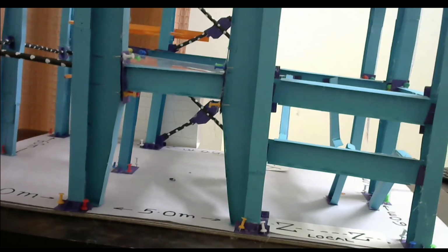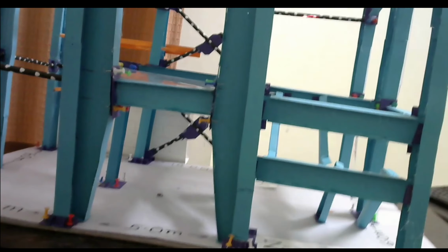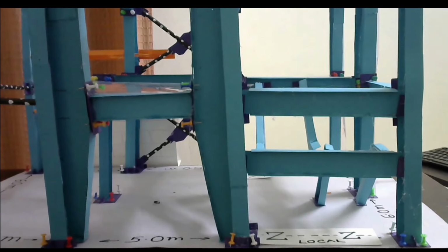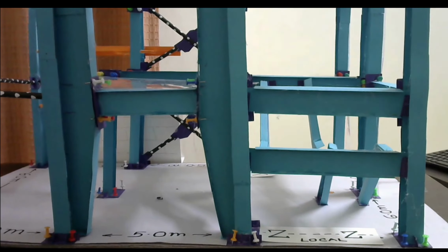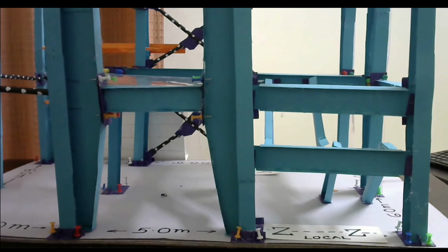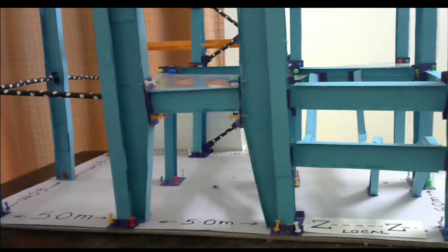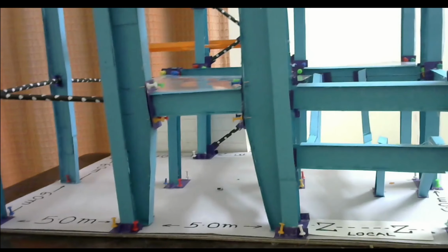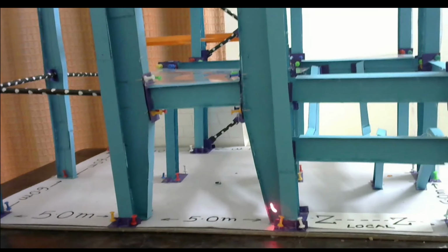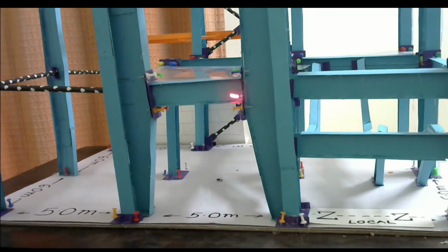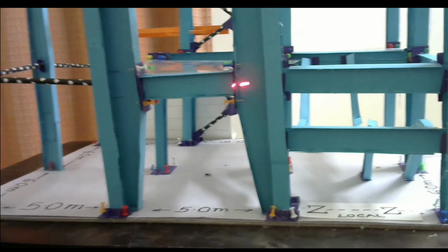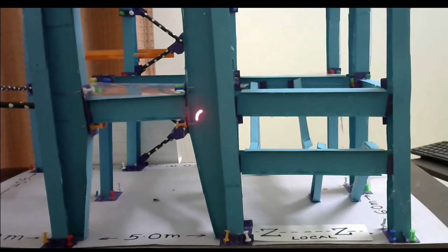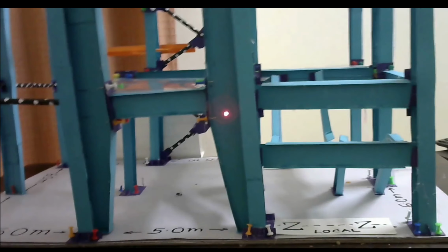It is a portal itself which is resisting the lateral force. So this is a sway frame, so we have to consider the case pinned at bottom and fixed at top. But before that, we must discuss the LX parameter also. So LX parameter remains 3 meter. There is a lateral torsional resistance here. There will be a stiffener here, so torsion twisting of this portal column is prevented. So LX is 3 meter.